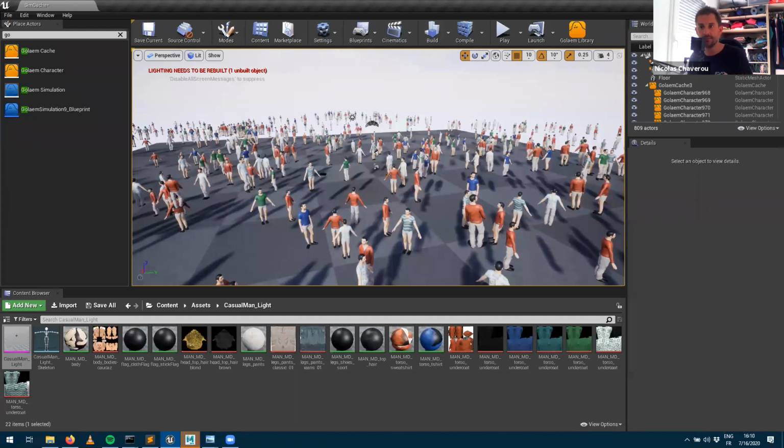You take the Houdini plugin or the USD integration, or within Maya, you just bring your characters as a geo or as geo proxies, which is a lighter version of the geo, and you can make your simulation and have your fluid reacting to that. One really casual example, if you need to generate the dust when the characters walk in the sand, which is generated by the footprints, you just bring your characters within Houdini with the Houdini plugin or with USD, and you generate the dust.